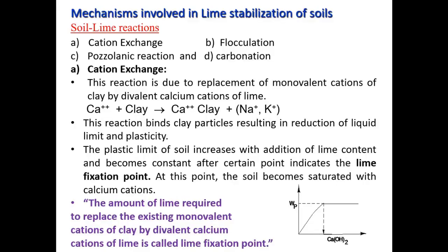Now let us see the soil lime reactions. When lime is added to the soil containing free silica, 4 important chemical reactions take place in the presence of water. They are cation exchange, flocculation, pozzolanic reaction and carbonation. First we will see the cation exchange.